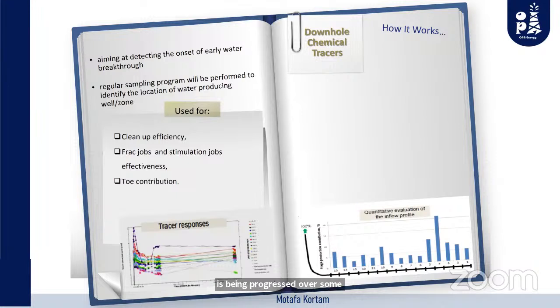So you may include a different, unique tracer in each well, and then you analyze the whole production line. You will get from it the tracer that belongs to the well, and then you will be able to understand which well is producing water and start to control the water from it.